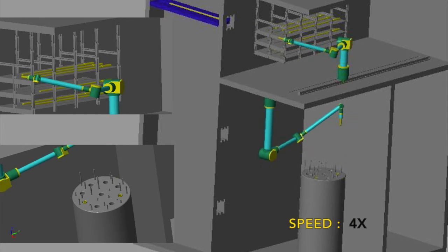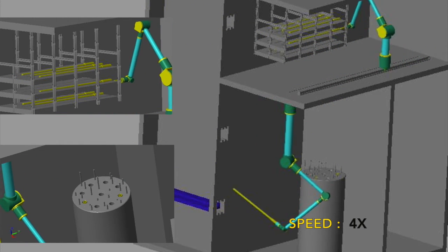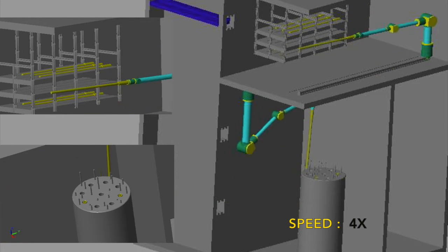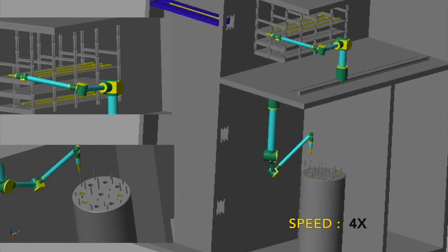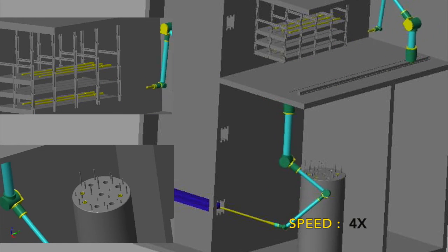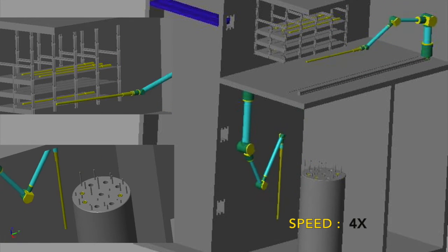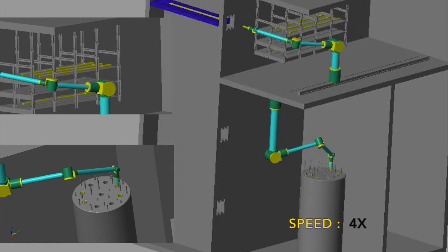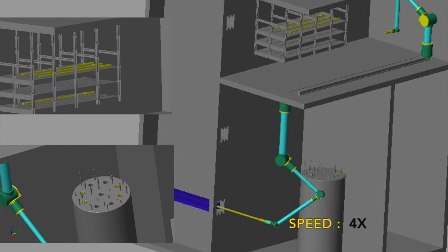In several situations, different techniques were required to calculate the path plan. ctraj was used to calculate a time-dependent trajectory of homogeneous transforms. Using these homogeneous transforms, the position and orientation of the end effector was controlled through an entire segment of the path. The inverse kinematics was run at each point along this path to generate the required joint angles for that section of the path.